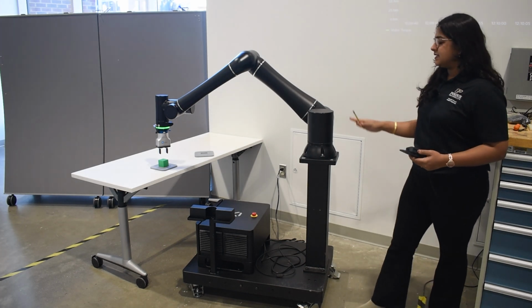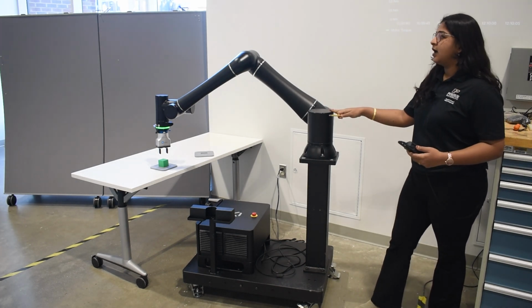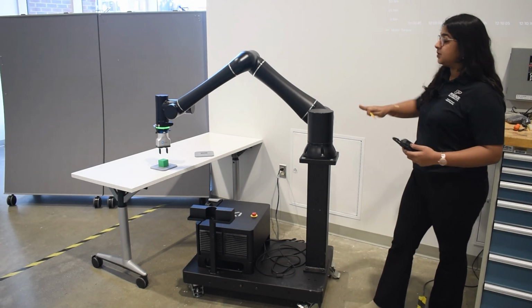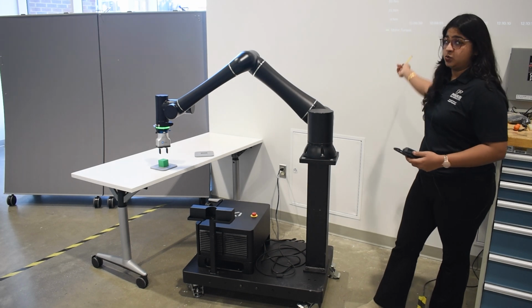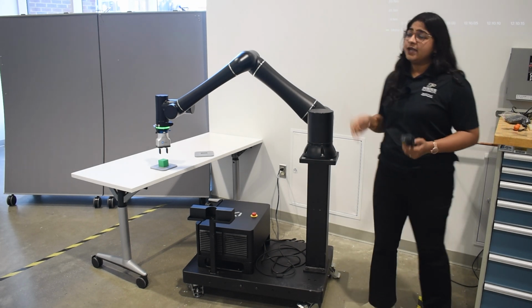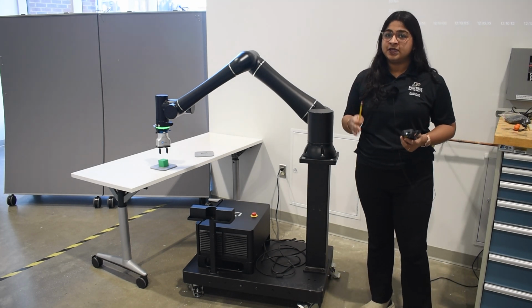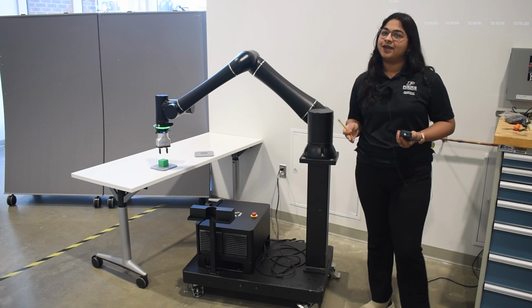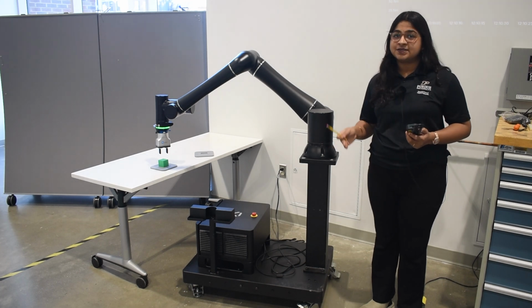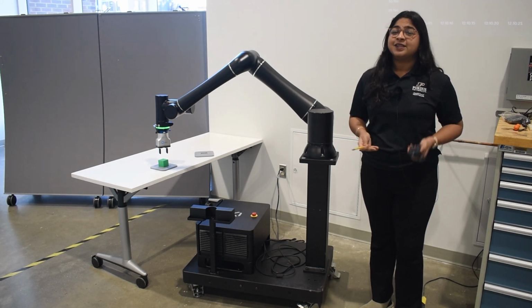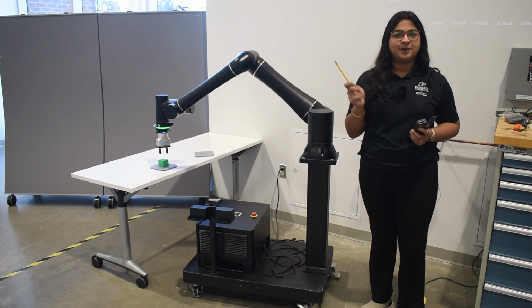In order to get started with actually measuring things, we need to first look at where the objects are placed in the extended environment. Here I can see that the robot base and the arm is placed very close to this wall, and so is its environment. I will be measuring everything with reference to this wall over here. The ideal way to measure things would be to have a LiDAR scanner and get accurate point cloud data and accurate coordinates. But if you're trying to do things on a budget, then all you need are good measuring tools and a pencil.